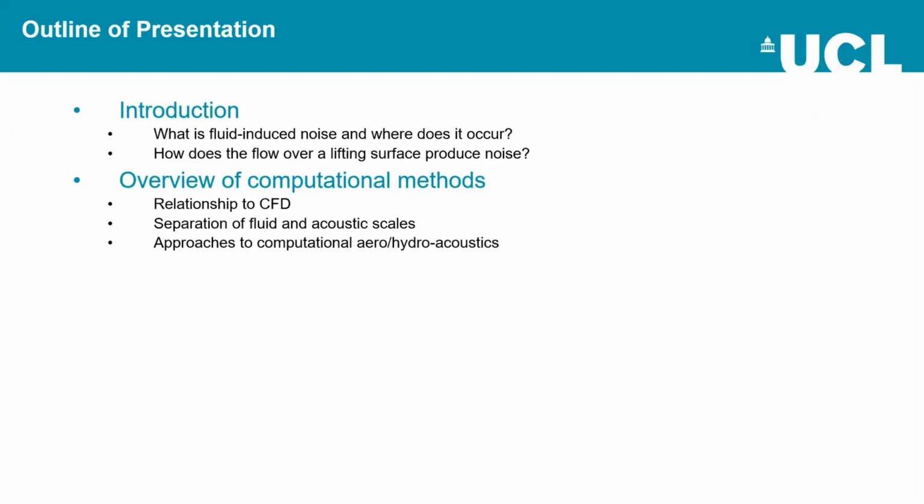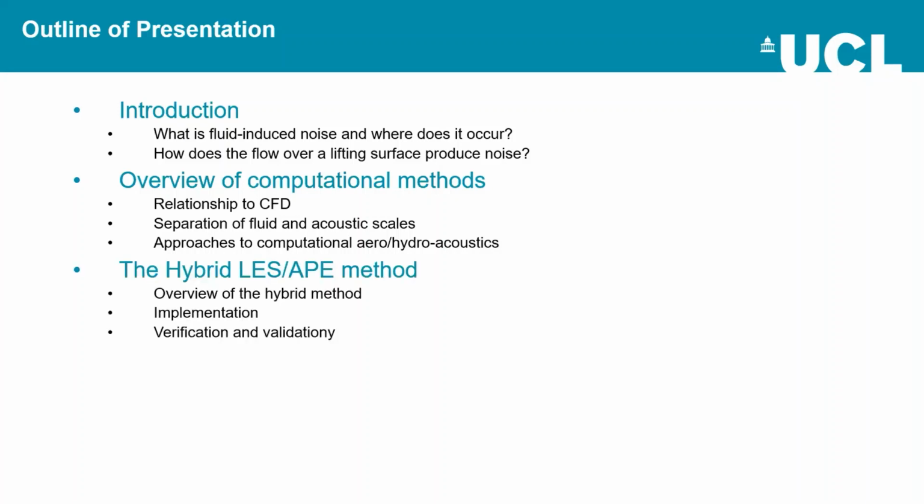I'm going to have a quick look at some of the different approaches that have been developed for computational aero and hydroacoustics. I'm then going to introduce the method that I've been working on, which is built on a number of previous works, which is called the hybrid LES-APE method. That's LES, Large-eddy Simulation, and APE is the acoustic perturbation equations. We're going to have a look at an overview of that method and how it's been implemented. So I've implemented it in OpenFOAM.